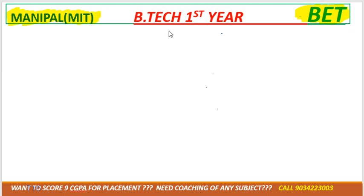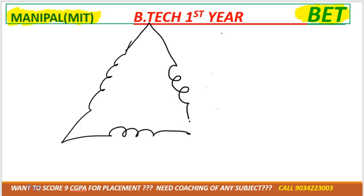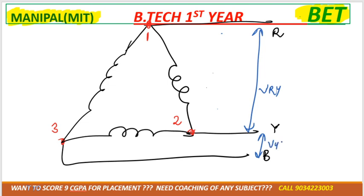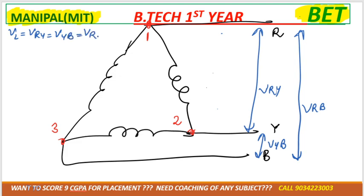Now let's go with the delta connection. In case of delta connection, as you know, delta looks like this. This is R, this is Y, this is B, right? So let us consider this point would be 1, this point would be 2, and this point would be 3. Now I'm marking the voltage. Voltage between R and Y would be VRY. Voltage between Y and B would be VYB. Voltage between R and B would be VRB. Now tell me, are these line voltage or phase voltage? These are the line voltage.